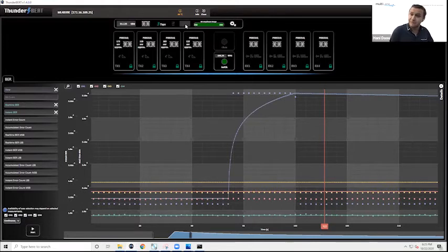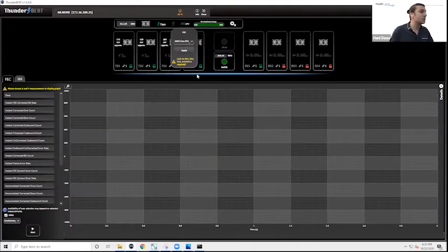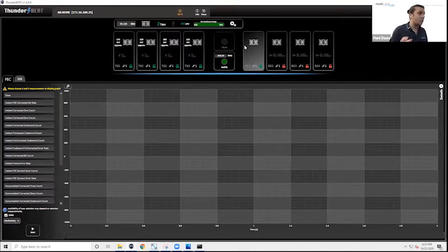And applying that FEC is as simple as going into the FEC tab and pressing apply. Now you'll see I actually only have one RX lock indicator. The reason is that by choosing 400 gig KP FEC, we have taken all 4 channels and squeezed them into one link. And that is really how FEC works in real life: the code words built by the FEC encoding scheme are striped across all 4 channels to create one link.